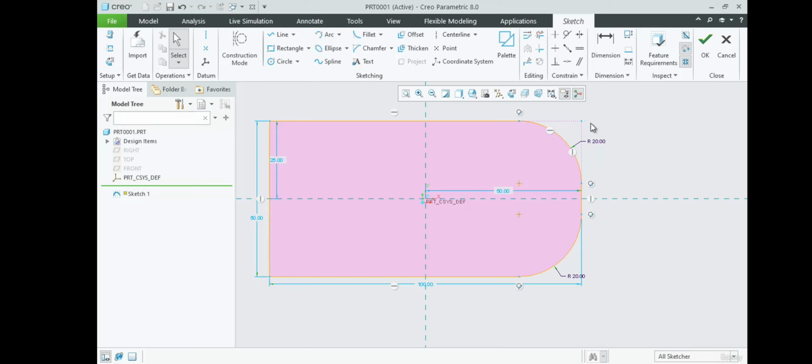In the first one, which is circular, it is creating 2 construction lines, which represent the lines that we have trimmed. And in the second case, both the lines have been trimmed and there is no reference element. That is, these construction lines are not present, and this point which generates due to the construction line we cannot get in this type of fillet, which is circular trim.